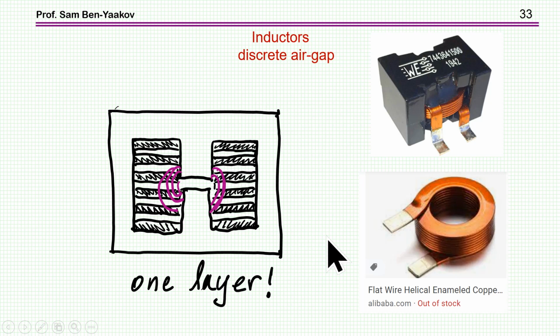which is becoming now more and more popular. And this is the helical winding. Okay, here's the winding itself. That's the wire. It's a flat wire, but it's put here horizontally, shown here. And the point is that this structure is actually one layer only. So this is actually one layer with the wires or conductors like pillars here, okay?